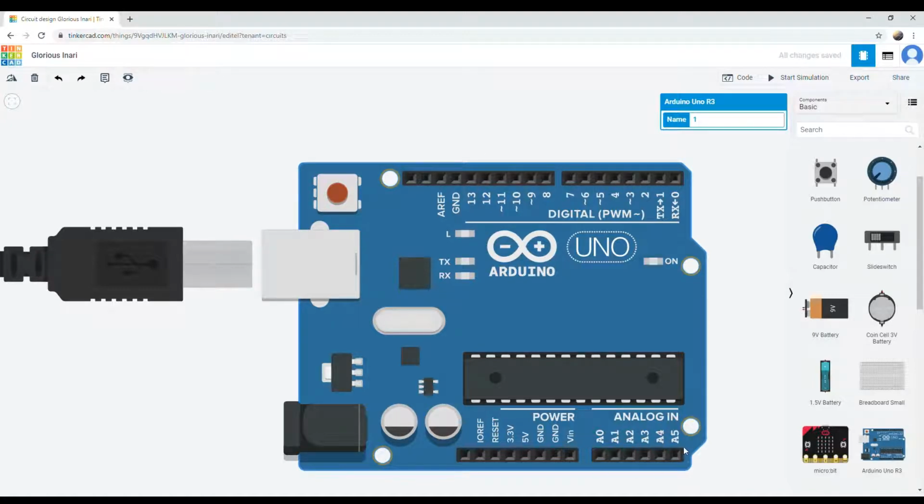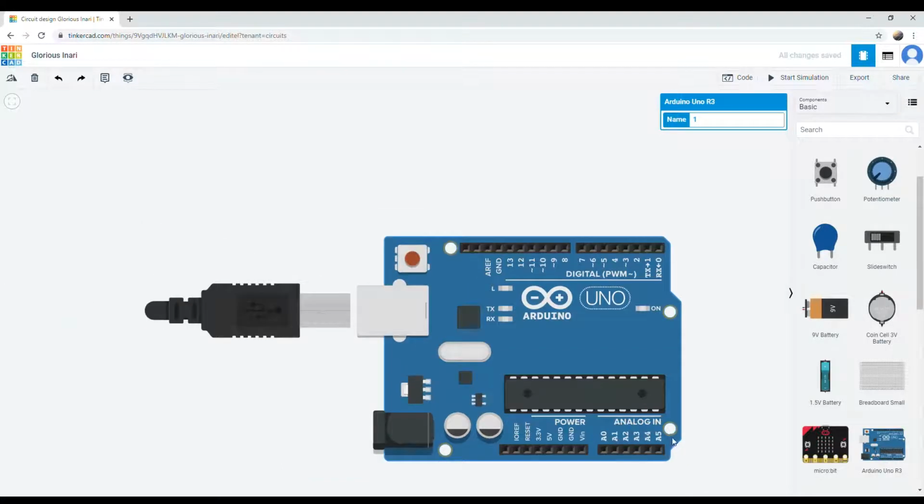This is the analog input. So if you have a temperature sensor that senses the temperature, or a variable resistor where you can adjust the resistance by the knob, this is not digital, this is analog. So you use it in this terminal. But if your application uses a switch, use a digital terminal. So it depends on the type of the input or output. If it is analog, use this terminal. If it's digital, use this terminal.